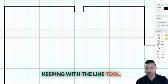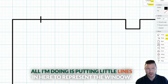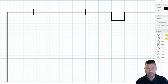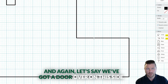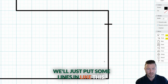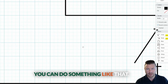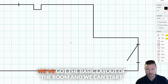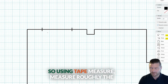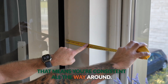Keeping with the line tool, again, if I zoom in here, let's say we've got a window. All I'm doing is putting little lines in here to represent the window. And again, let's say we've got a door. Over on this side, we'll just put some lines in like this. And if you wanted to show which way the door's opening in, you can do something like that. So nice and straightforward. We've got the basic layout of the room and we can start putting measurements in. So using tape measure roughly the middle height of the wall. That means you're consistent all the way around as you go.